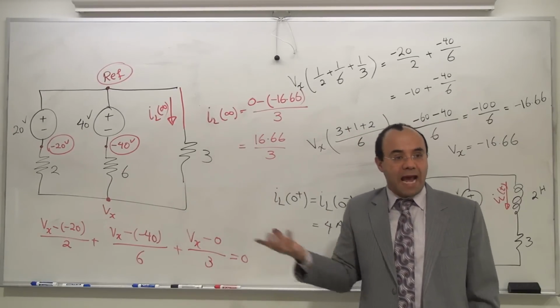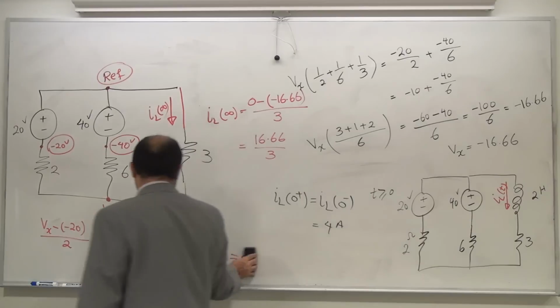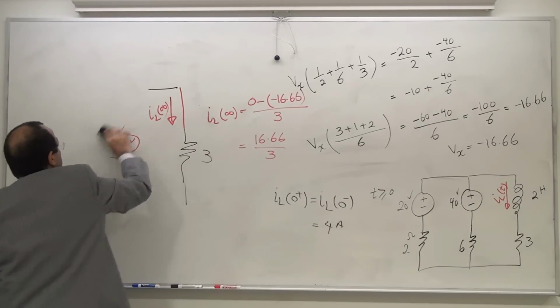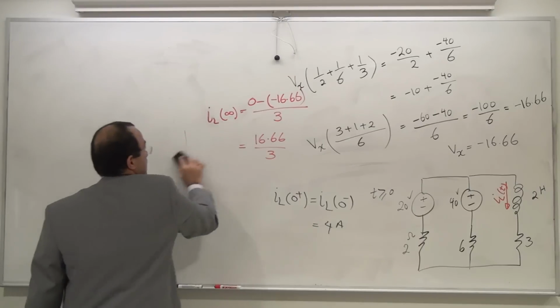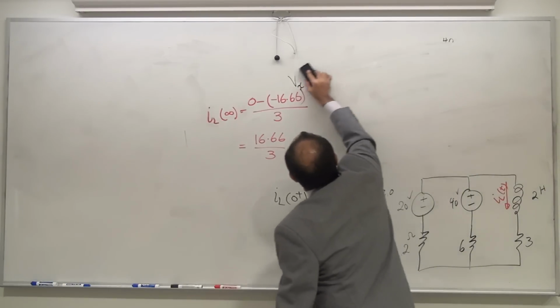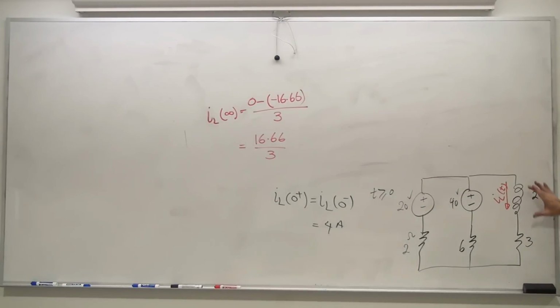Then you need to find tau. Let's go and find the tau. I'm assuming everyone can pause the clip and see all the calculations. Now I want you to stand across the inductor. The inductor is not short, the inductor is not open, the inductor is just behind you. I want you to remove it for the time being, and see what the inductor sees.